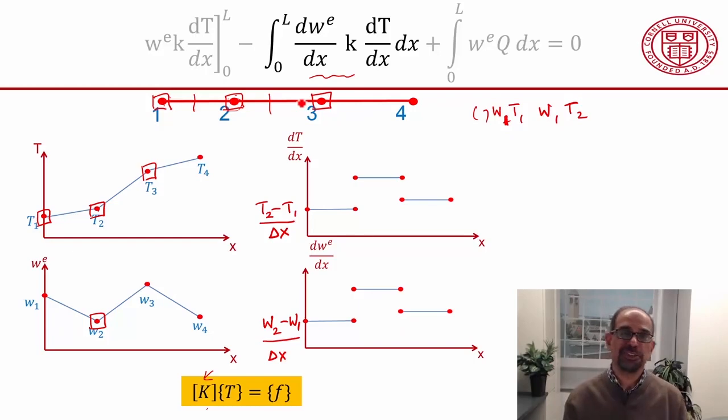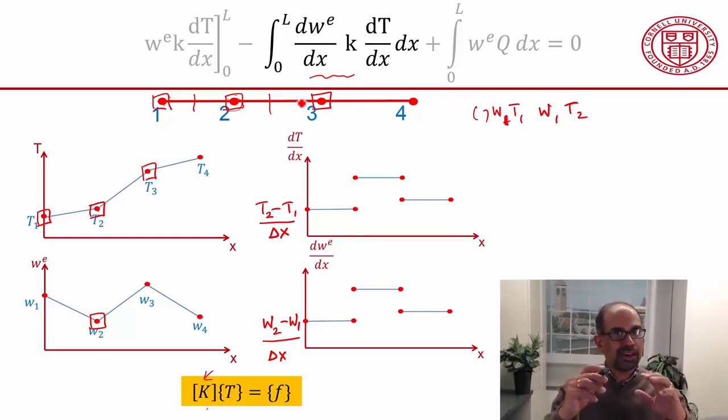And I can generalize this. So I have this complicated mesh in ANSYS, and I'm thinking, okay, this node is connected to these elements, and those elements in turn are connected to these nodes, and so I know ANSYS will write relationships connecting the temperature at that node, or displacement when we go to structural mechanics, to all the corresponding nodes. And I feel like that's very useful when I'm in ANSYS.